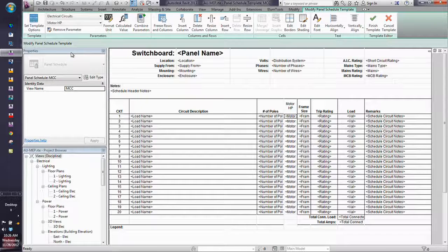If I assign it to the electrical equipment, will it automatically populate the circuit schedule? No, it doesn't do it automatically. Even if you go in and try to edit it, it's still a separate field and you can't link the two of them together. The way we're handling linking it is we actually export this stuff out to a spreadsheet or a database and then sync the two of them together. That's one quick way that we can do it, and we keep track of a lot of this stuff outside of the program. That way, once they're synced, we can drop them back in and they stay current.